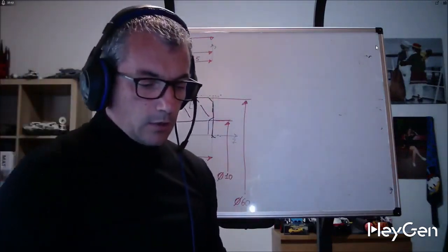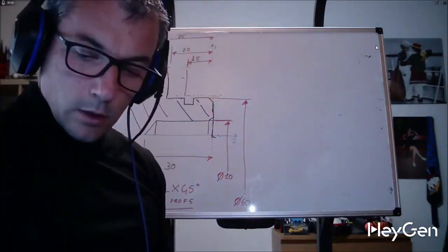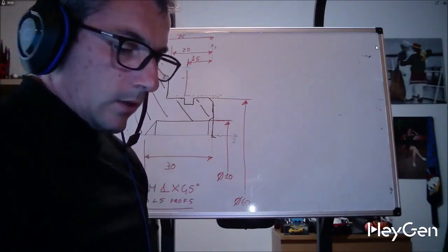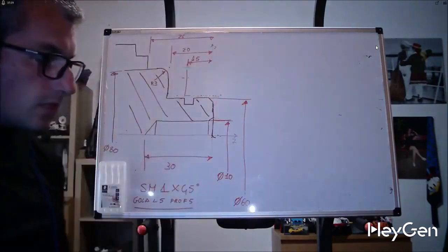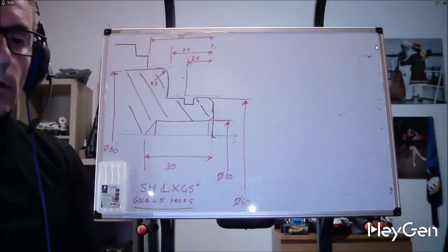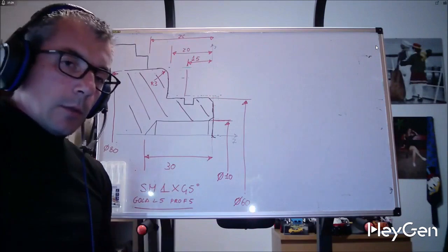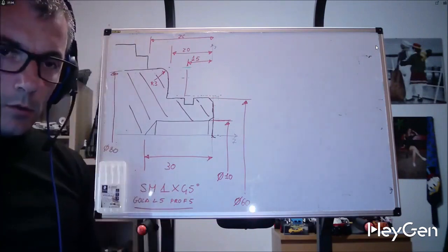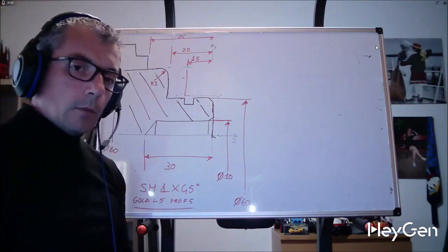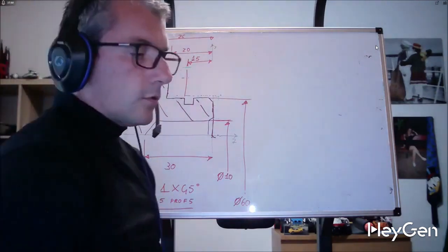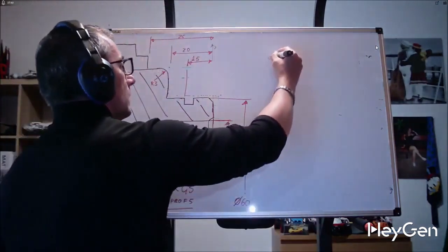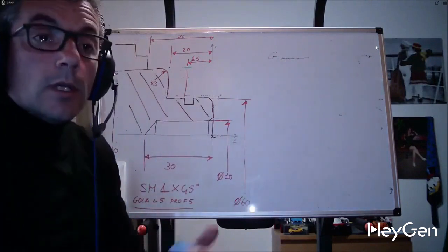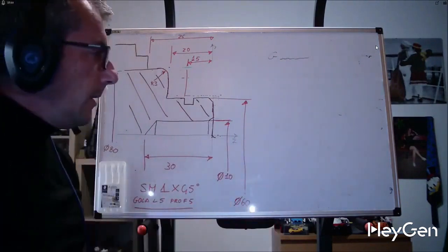Roughing, long axial roughing, drilling with chip breaker, cycle for front grooves, radial grooves, threading. I would say that fortunately these cycles are better oriented, a bit of everything. So now remember that our programs will become a sequence of X and Z, alternating between fixed cycles and X and Z. The fixed roughing cycle, for example, is identified by a G that identifies the cycle. I won't write down which G it is now, because it changes if you change CNC.